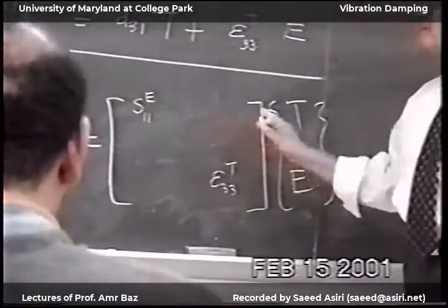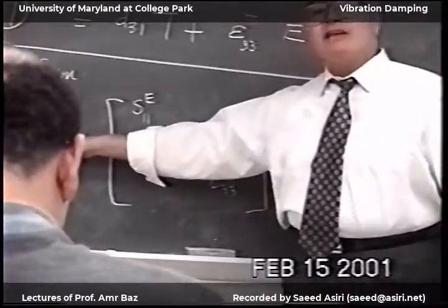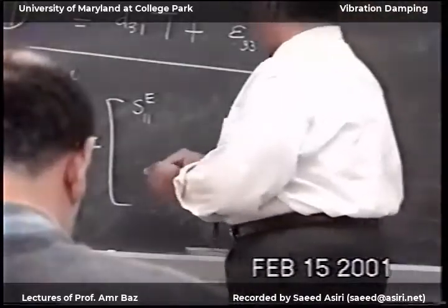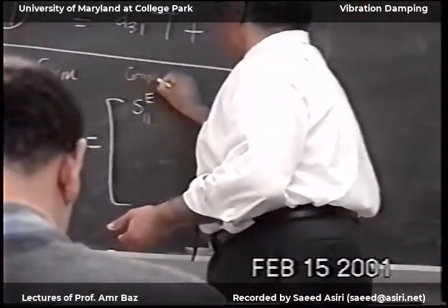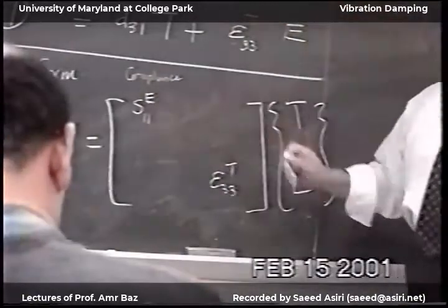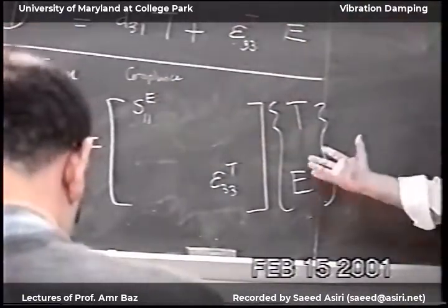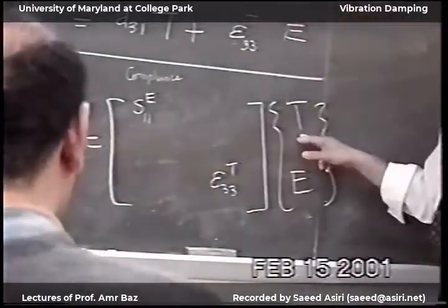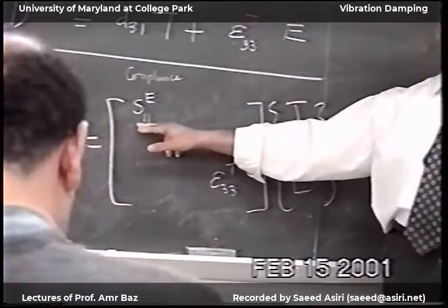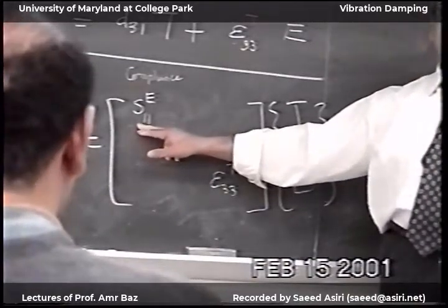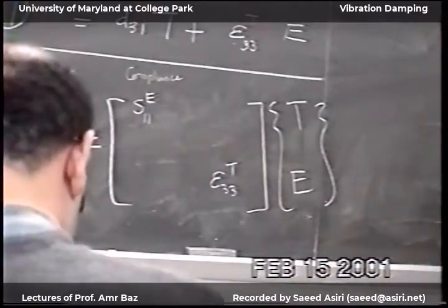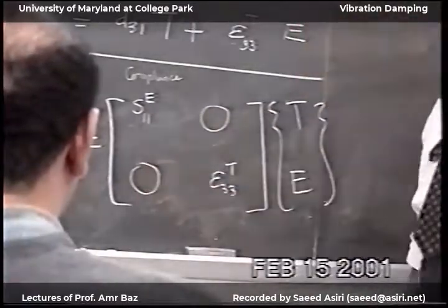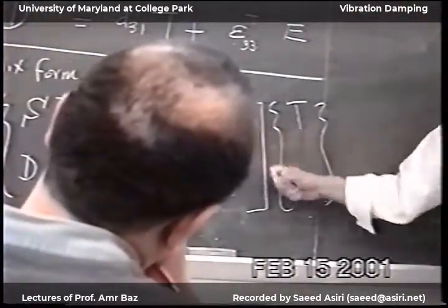So if you look at the terms that I have now, the strain is related to the stress by the compliance at 0 voltage. For regular material, that's all that we have. I can generate the strain by applying stress, through the stiffness or the compliance of the material. And usually these materials have 0 at this term. It does not depend on the electric voltage.